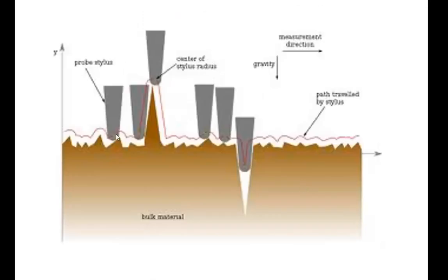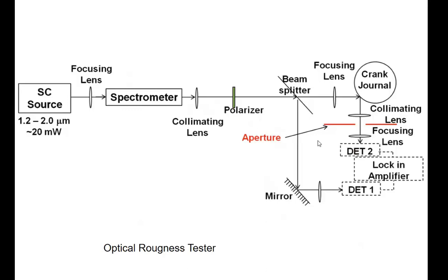The stylus follows the irregularities along the path. When it is in contact with a protrusion, it will be raised. If there is no protrusion but a cavity, it will drop. So the displacement between this and that is recorded by the instrument. Okay.